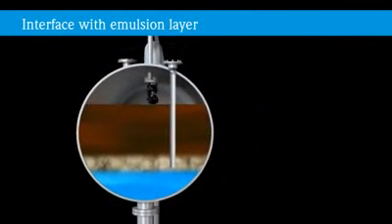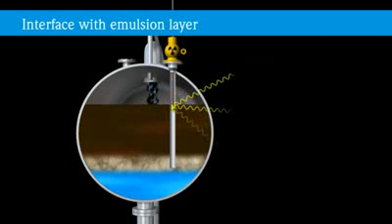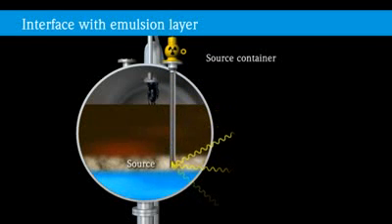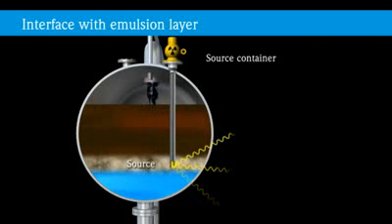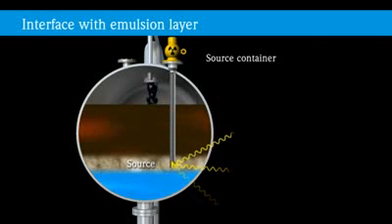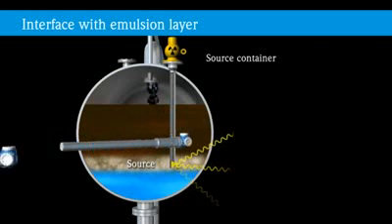Separators usually have a diameter of several meters. In order to keep the activity of the gamma source as low as possible, it is inserted into the separator. The gamma source is enclosed by a protective tube and positioned in a closed immersion tube. This excludes any contact of the radiation source with the medium.